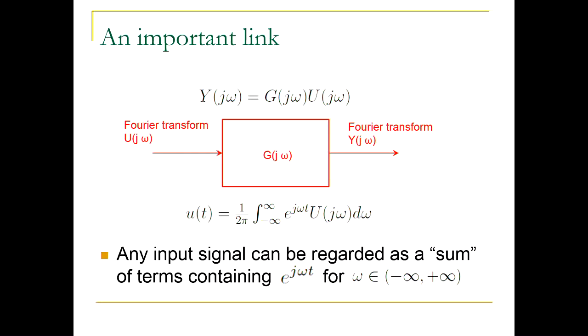Because of linearity, I can find the steady state of this system response to each of the individual inputs, and then sum up these individual components to find the steady state due to that sum of sinusoids. Similarly, if you have a Fourier transform of a signal, it's like infinitely many frequencies, but because of linearity, I can just add the contributions of each of these.